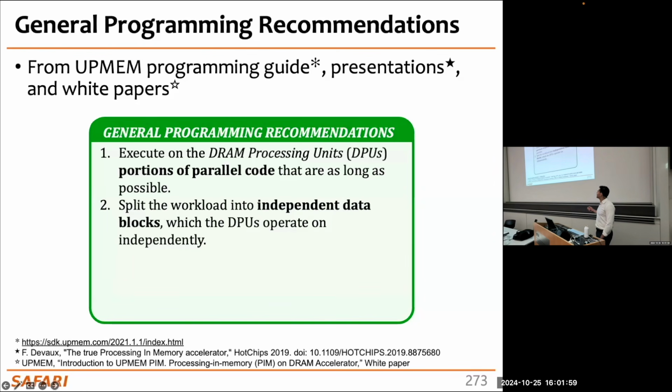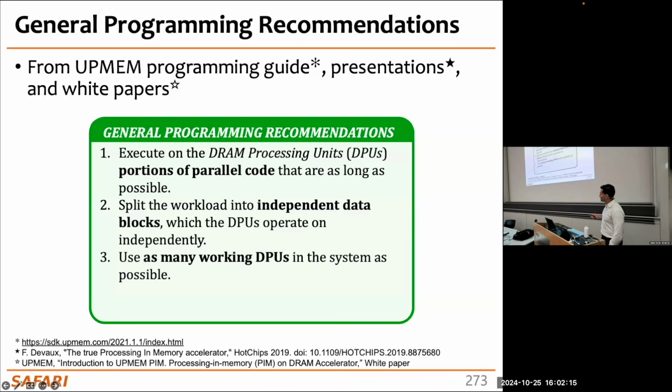You also want to find data-independent blocks which the DPUs can operate on independently, because the moment they become dependent, you're going to have to move data from one DPU to another, and moving data like that requires you to go to the CPU, and this is going to incur extra latency.